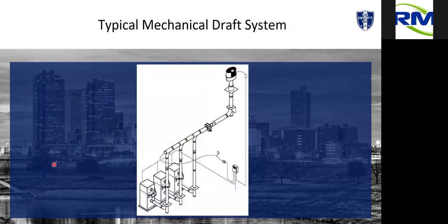Basically what we do is we put a damper in line to create false back pressure. In this case, we have both a fan and a damper. As we need draft, the fan will ramp up, modulating up to maintain that negative. As draft exceeds where it needs to be, the fan will start to slow down and get down to its lowest speed, and then we'll start to choke it off with the damper. Those two work in concert with each other so that they're not fighting each other; they're actually accentuating each other.